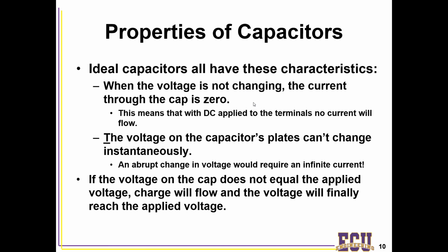So if you're not charging up the capacitor, if the capacitor is already fully charged to where, let's say you have a voltage source and the capacitor has the same voltage at this point as the voltage source, it's now going to behave like an open circuit.